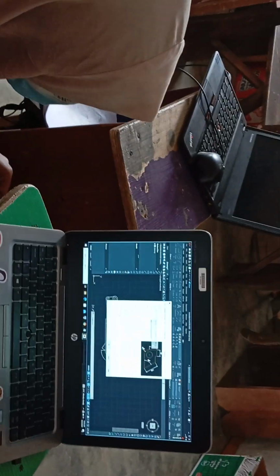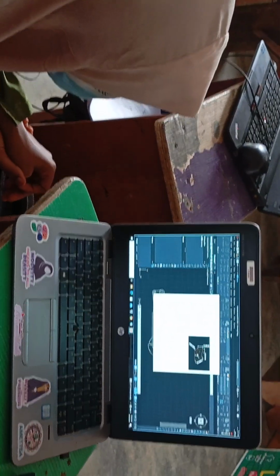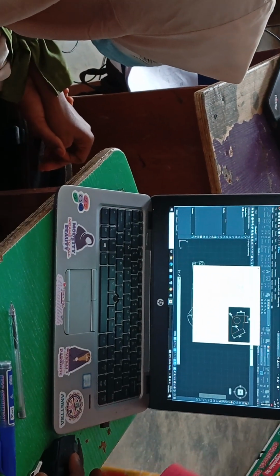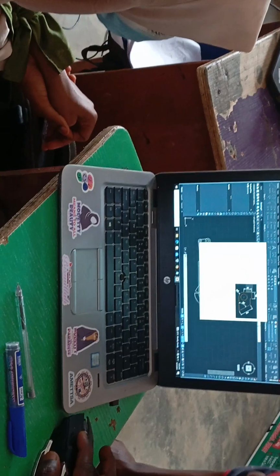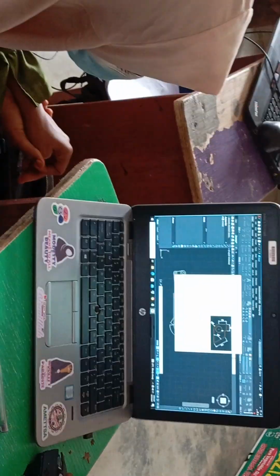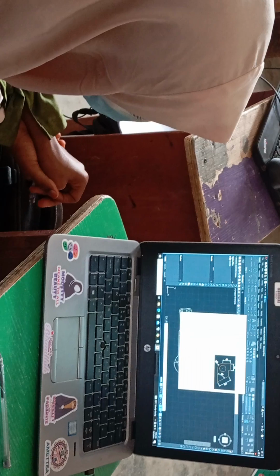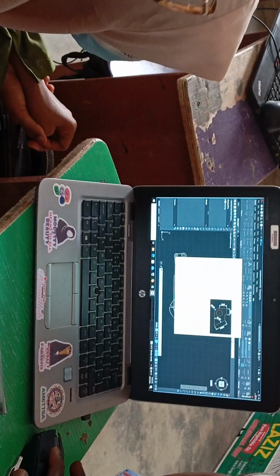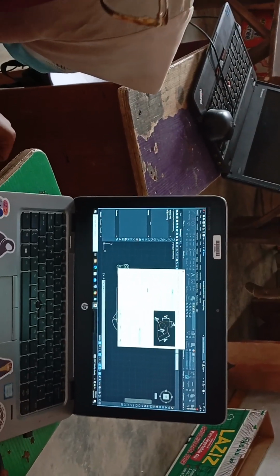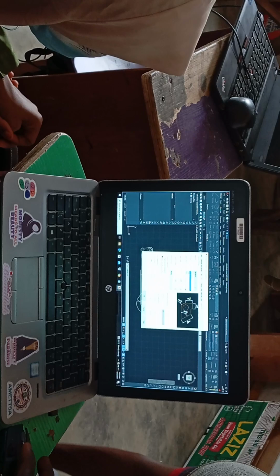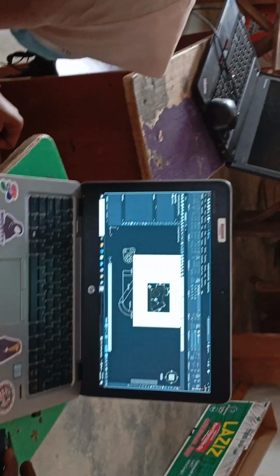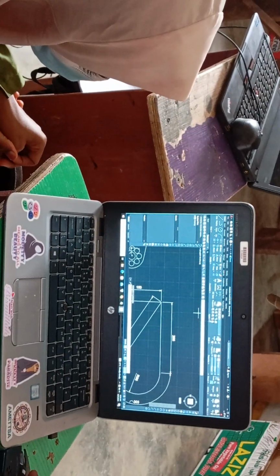Alternate units. If you click here, if you are working in millimeter, it will give you alternate in inches and feet. If you are working in feet, it gives you alternate unit in millimeter and meter, as the case may be. You don't use it most of the time. It makes the drawing look awkward and populates the drawing unnecessarily. Tolerance, not necessarily, the method is none. But sometimes you may want to put the symmetrical value or the deviation plus or minus, depending on the nature of the drawing. Let's leave it at none. Say okay. Having done that, I click OK, I click close.